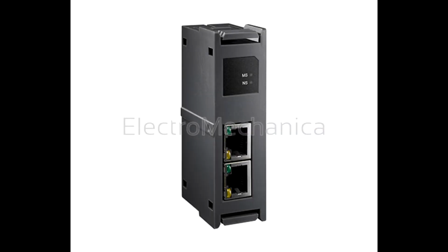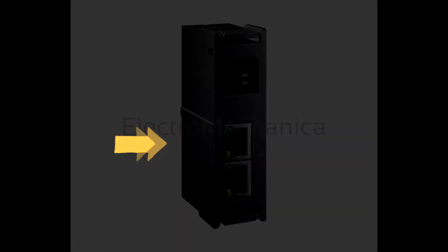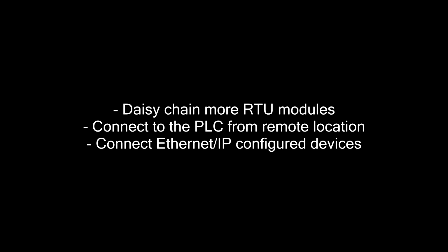The AS0102 communication card uses both card slot 1 and 2 when installed in the AS00SCM module. The two RJ45 ports on the communication card act as a 2-port Ethernet switch. This means that you can use the second port to daisy chain more RTU modules, use it to connect to the PLC from the remote location, or even use it to connect Ethernet IP configured devices such as HMIs and